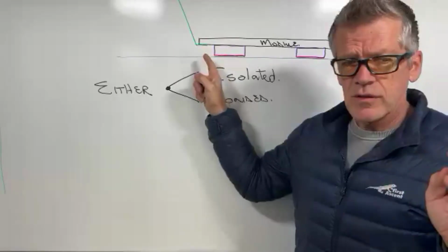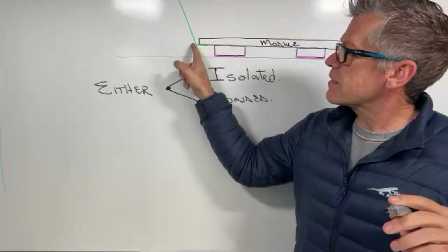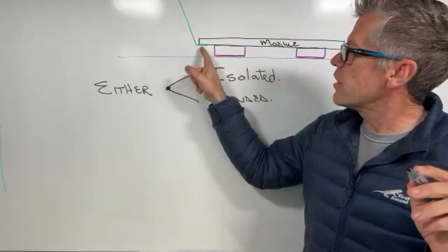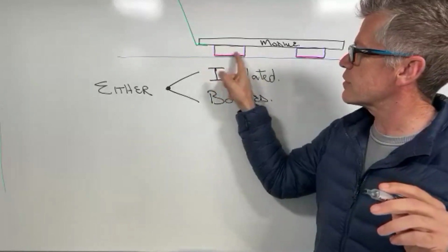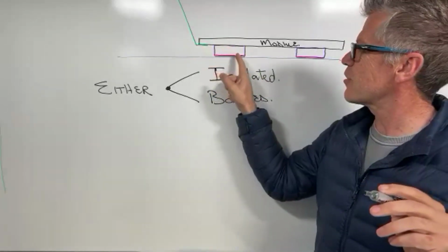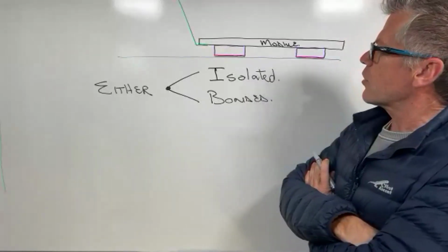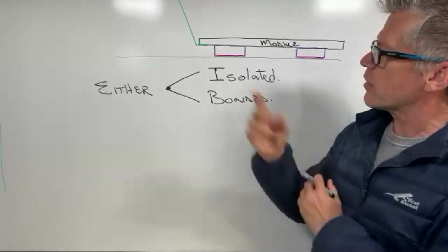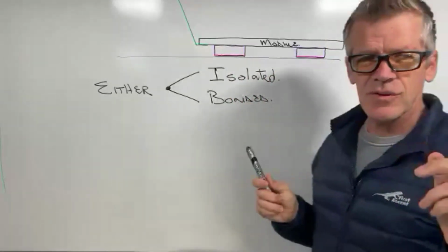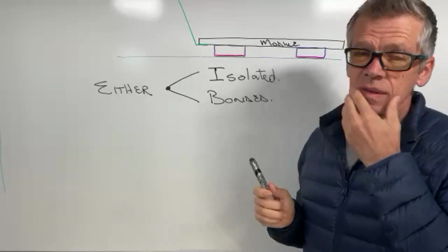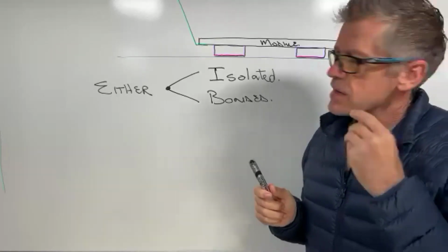Correct. Yes, absolutely. The other thing you mentioned is if we have a lightning strike over here, there's absolutely nowhere for the surge to go because this is insulated from the roof. So where I'm going with this is you mentioned something that you call the separation distance.